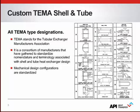The integral tube sheet of this design also allows for a small diameter and thinner material with one less flange joint. So in general, the more flange joints you have, the more costly the design will be due to additional weld seams, gaskets, and bolting. On the shell types, E is by far the most common, simple one-pass type shell.